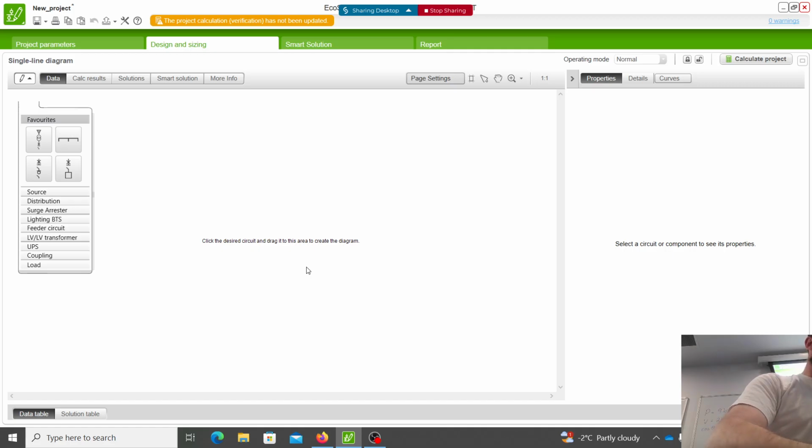To go back to what we looked at on, I think it was probably the first set of distribution notes, these will be labelled using that notation for three-phase, neutral and earth. And our load is what, single or three-phase? Yeah, single phase. And there'll also be some protection devices listed on that single line diagram. So again, just like what we did at the start of distribution, it's a way of looking at an electrical installation. It's telling me we have a source, three-phase cable, bus bar, single phase cable, down to our load.